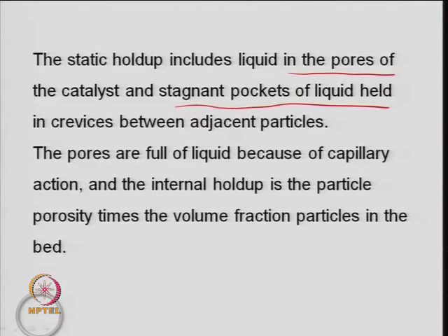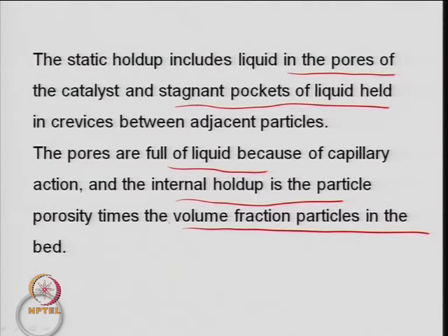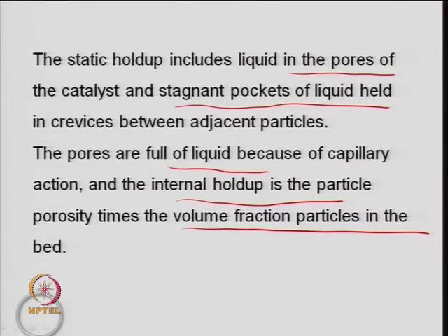The pores of the solid are full of liquid because of capillary action, and the internal hold up is the particle porosity times the volume fraction of the particle in the bed. If you know the particle porosity and the mass of the catalyst in the bed, we define it as the porosity of the particle multiplied by the volume fraction of the particle in the bed, that is, the volume of the catalyst divided by the volume of the bed. So, one can very easily calculate this static hold up, because it is nothing but the volume of liquid present in the pores.